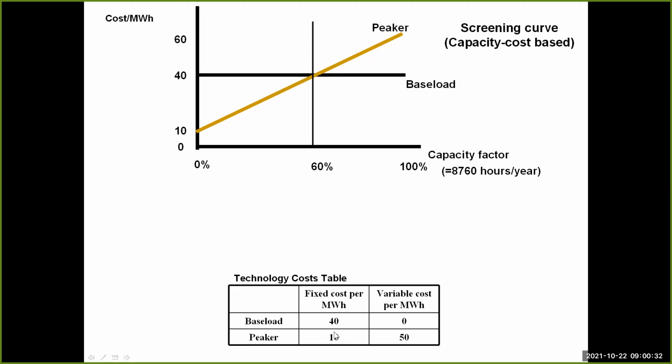Now you see, even if you just added up these numbers here, then you were actually assuming that this plant would run 100% always. But this is not possible if you have a load duration curve that is anything different than a block figure. We have different demands during the day, and therefore you cannot run the plant you build 100% of the time.